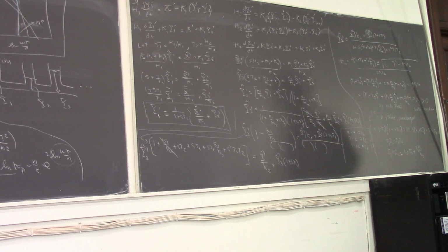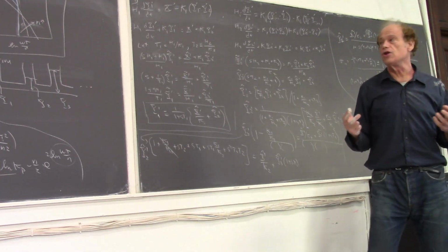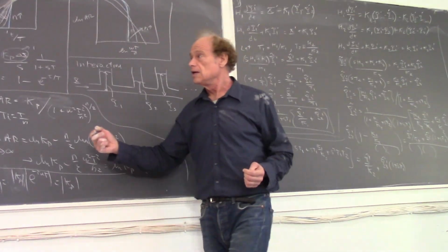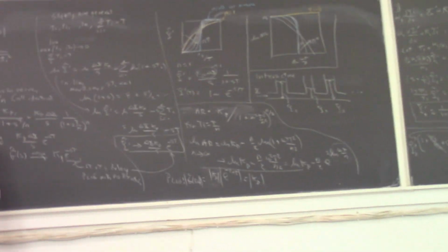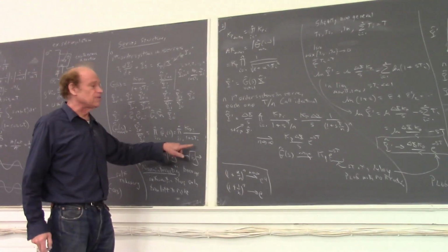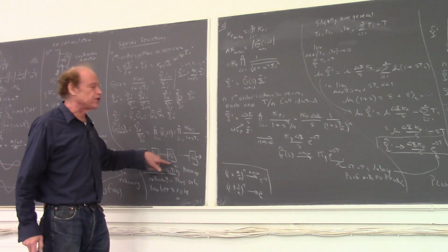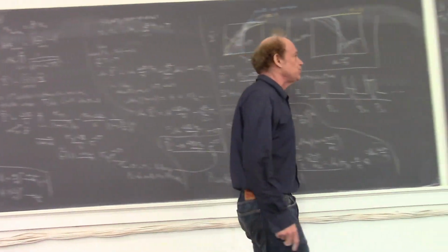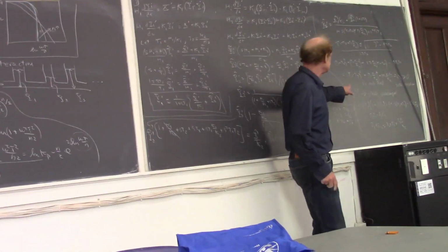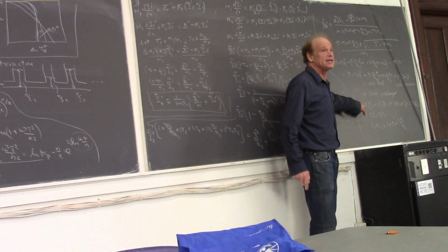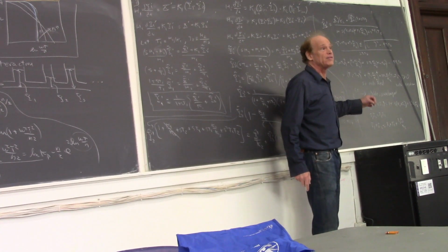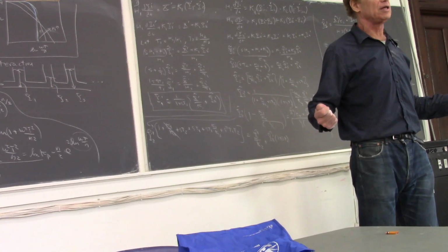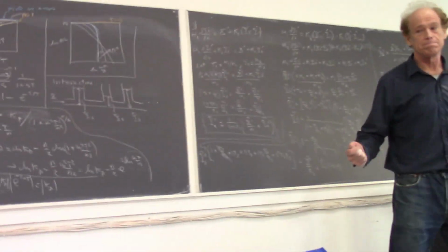Are there questions? So again, the basics is the interacting systems are quite different from the non-interacting. In the non-interacting system, the time constants are just the time constants of the individual systems. In the interacting situation, the time constants are the sigmas, not the t's. And the sigmas have a faster and a slower one. They're more sluggish than the non-interacting system.